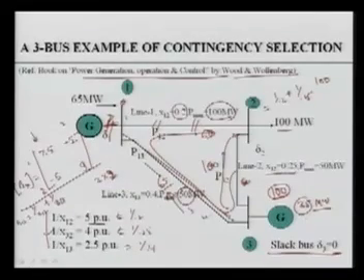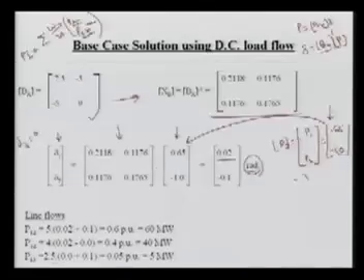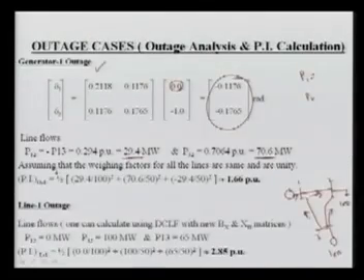This line has a rating of 50 megawatt. Meaning it is 1 per unit, 0.5 per unit, 0.5 per unit again. So using this, you can divide by the megawatt value or use per unit, of course no difference. So this divided by this square plus this divided by 50, this again with the minus value we are just taking, square of 50, and you get 1.66 per unit.